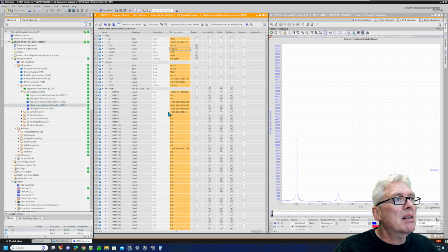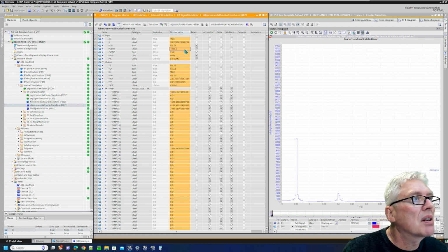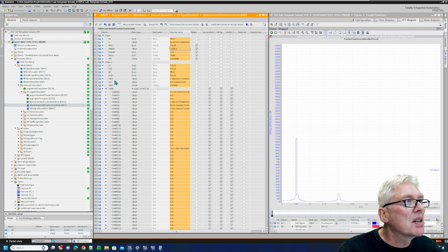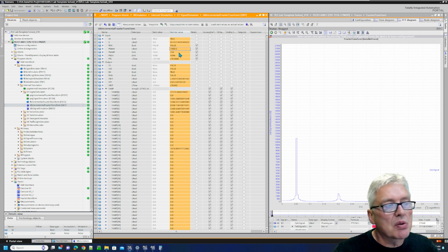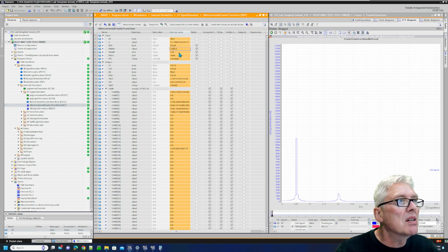And this is incremental, so it does the calculation rapidly. And here for these 4096 samples, the processing time is around 2 milliseconds. This just indicates it's active, and this is the sampling output. You can see once in a while there's a configuration error if you do configurations up here, so it doesn't match. I calculate 256 amplitudes. The maximum is 32,000.